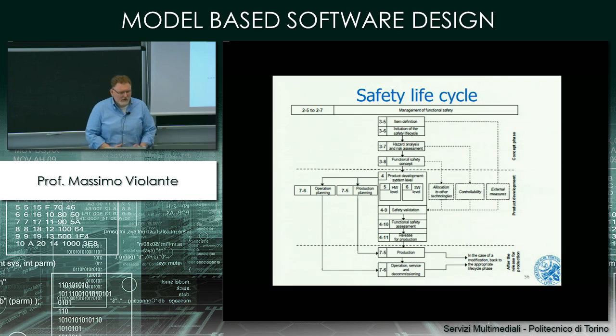It is a degraded mode, according to which the ABS works on either the 2 front wheels or the 2 back wheels, producing the same corrective action. So we have the full operational mode, used when everything is working correctly. Then we have a degraded mode that is used as a complement to the full mode when a fault has been recognized.